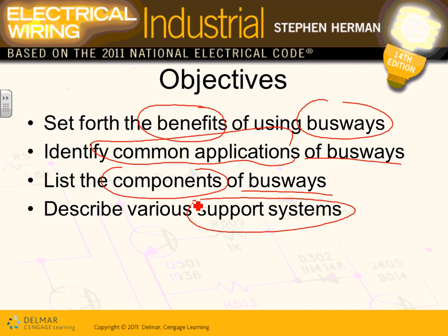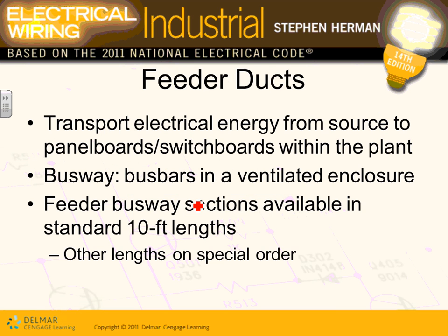There's a lot of weight on them. So when you put in a busway system, you have to talk to your structural engineer. Can you mount this busway from a wall? If you mount the busway from a sheetrock wall, it will take that sheetrock wall down with it. So you have to pay a lot of attention to the structural integrity of the walls and the ceilings before you start mounting busways to them. Big deal.